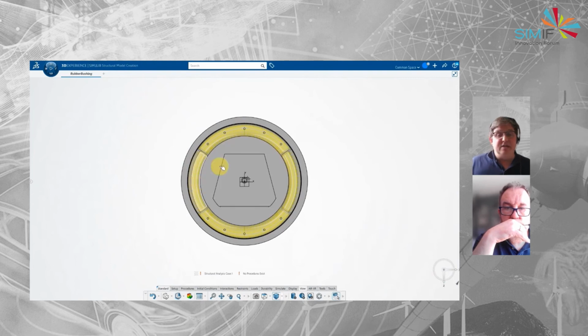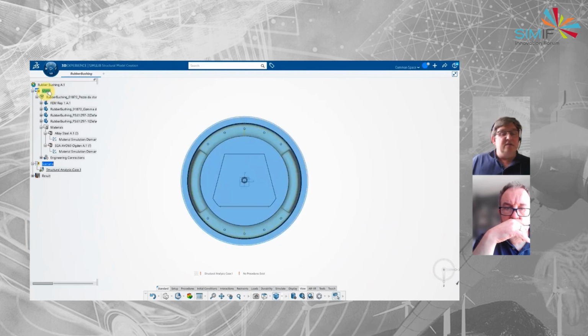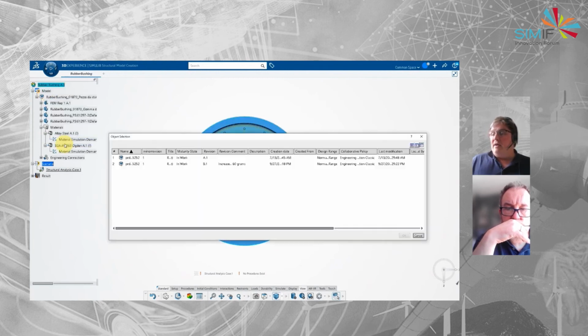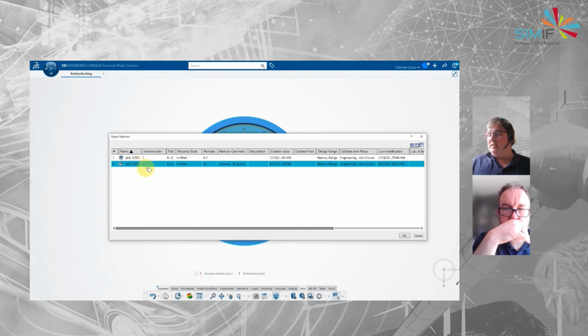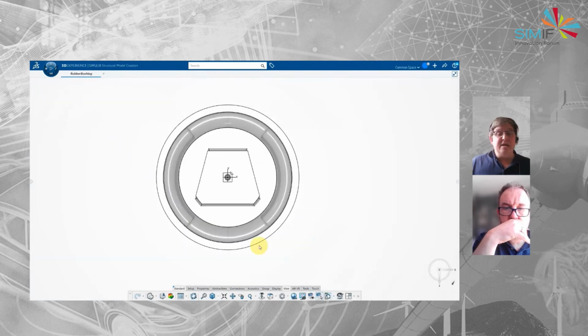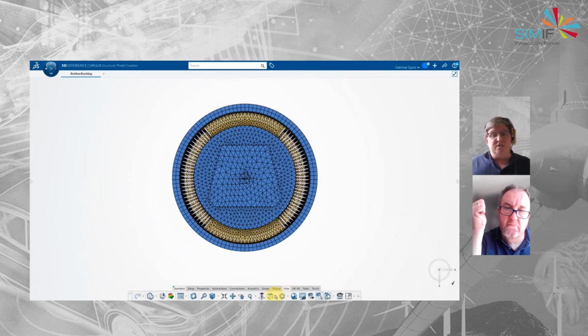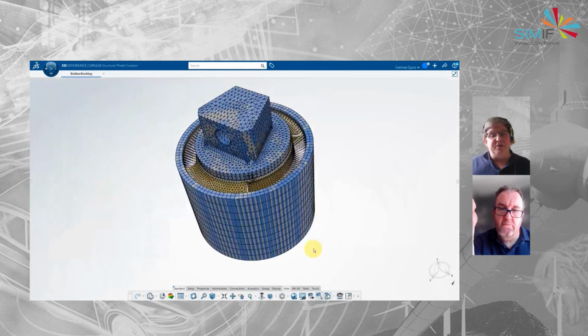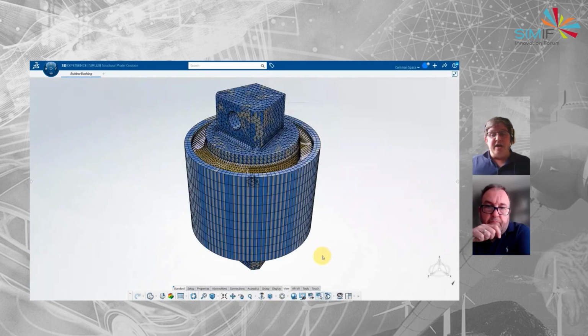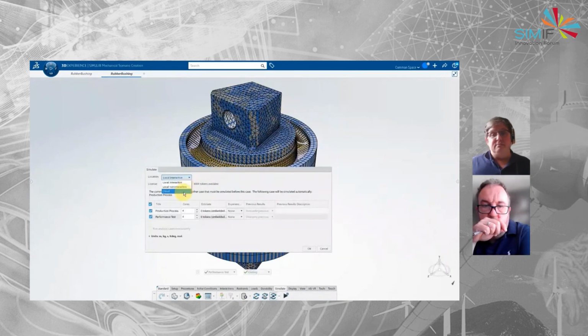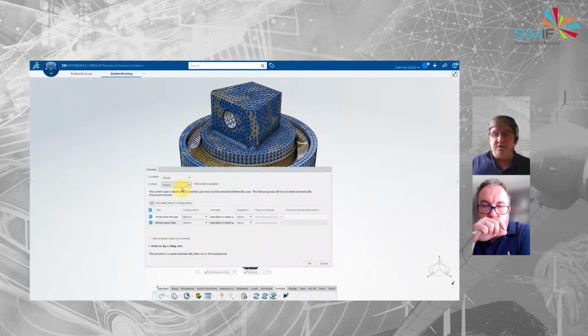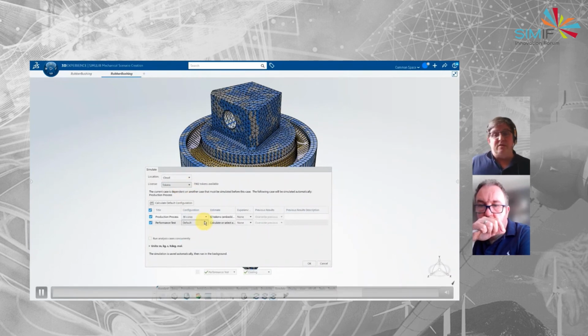So now in the simulation world, we can see that we've got an update available to change the bushing to a B. So now we're going to just swap that out, exactly like Barry says. All of the setup work's been done for us because we did it in the previous simulation. So now it's just a matter of rerunning the test in exactly the same way, 36 cores again, and saved ourselves a host of time.